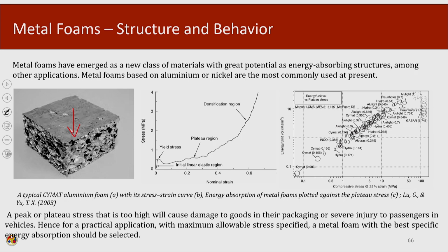As we can see, as for any other material, the elastic phase is there, after that the plateau region occurs, and after the plateau region the densification region occurs. A peak or plateau stress which is very high will cause damage to the goods in their packing or severe injuries to the passengers in the vehicles.